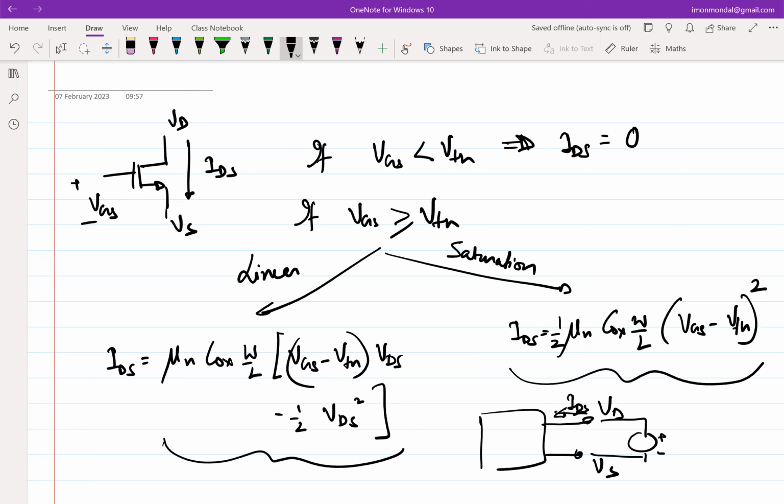The current doesn't change even if I apply a voltage source and try to change the voltage. What does this remind you of? Y22 equal to 0, great. But is it like a voltage source, a resistor, or a current source? It's a current source, right?